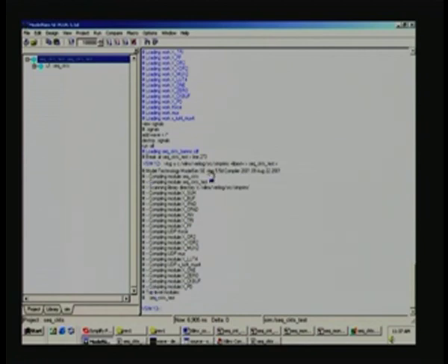This is a result of including the entire Xilinx library here, and thereafter you had to have the test bench also compiled, and that is already done here. Prior to this it compiles your design. Actually, this is a back annotated design, and this back annotation is not specifically mentioned, because what we had declared as a module is actually sequential_circuits in the design. So, we did not change the module name, and what it reports is only the module name, as you see here.